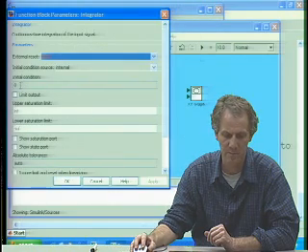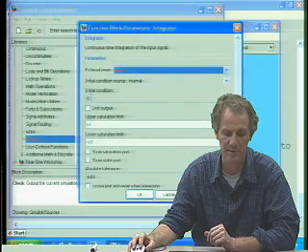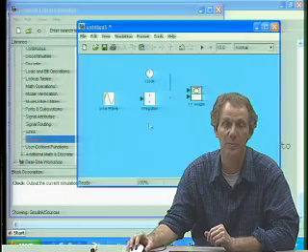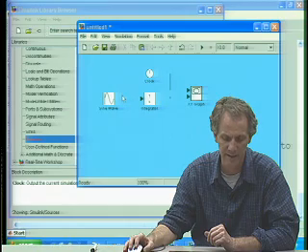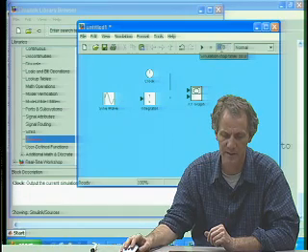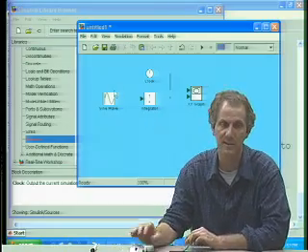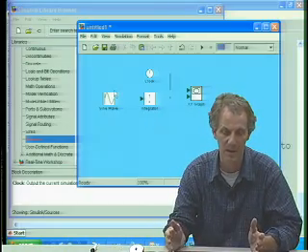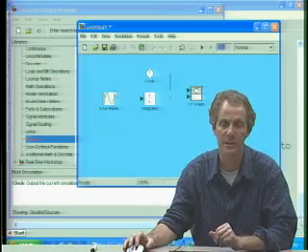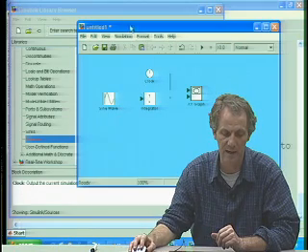When I double click on 1 over s, I can put in the initial condition. I'll leave it at 0 for just a moment. And I think that should do it. I need to pick the amount of time I integrate for. There's a simulation stop time. 0 to 10 seconds is good enough because this sine function has period 2 pi.